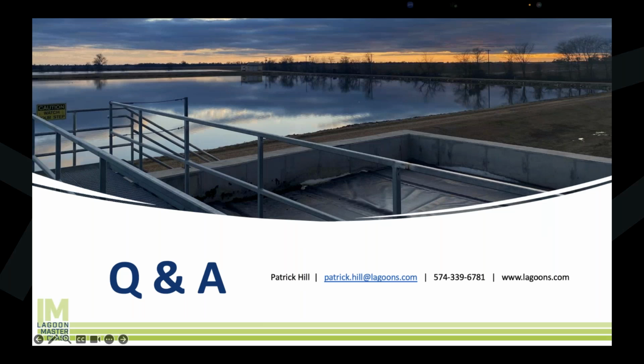Is there a type of probe you would recommend over others for testing, like Hach meter or other brand? So for the DO probe, the one that's most common that I've seen is the Hach one, but YSI also makes a DO probe that you can attach like pH, and most DO probes will do temperature as well. I wouldn't recommend any of the ammonia probes. Ammonia probes are not really designed to give you super accurate data on ammonia, especially at low levels, which, in the grand scheme of things, most lagoon ammonia is pretty low anyway, even if it's at 30 milligrams per liter.